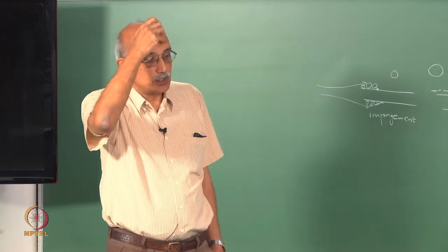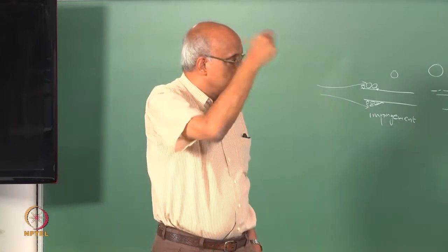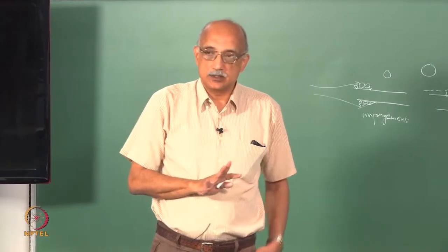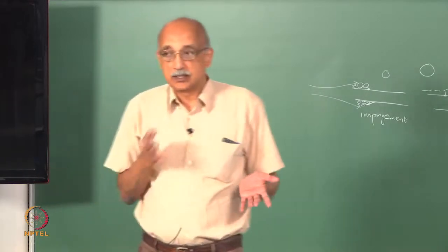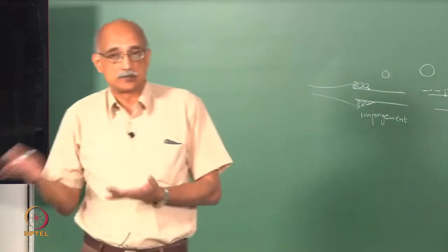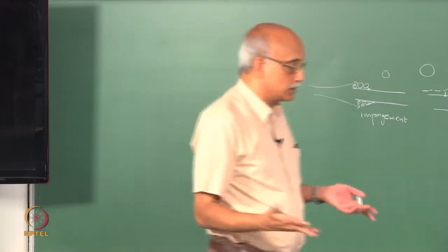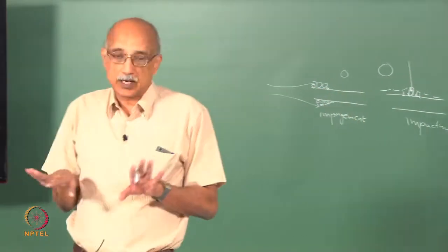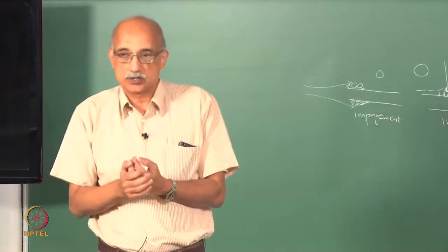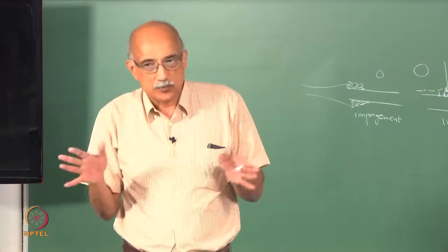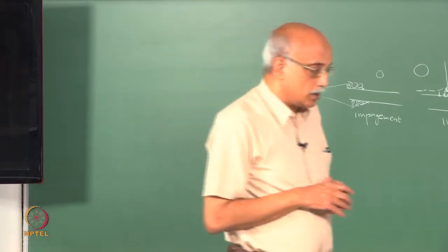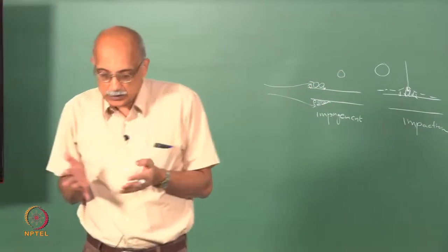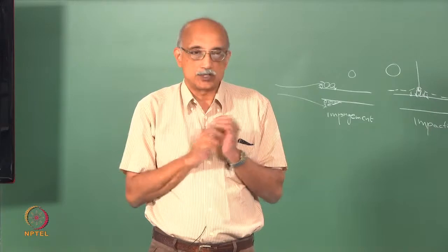So, by using this kind of an arrangement, you can once again simultaneously collect and classify. Again, the difference is collection is simply collecting all the particles that are suspended in the fluid. Classification is separating them by size as well. So, clearly if you are going to be doing subsequent analysis to determine the size distribution, it is very convenient if you can, as a part of your collection process, also separate them by size, at least approximately, because when you talk about static methods of analysis, there are different methods that can be used depending on the size range of the population you are looking at.